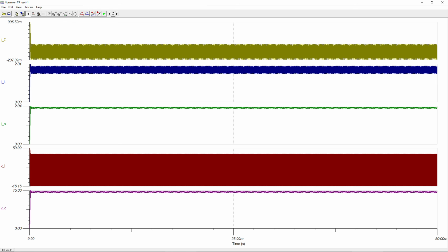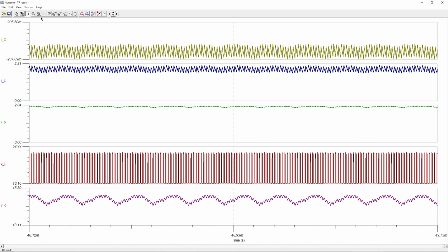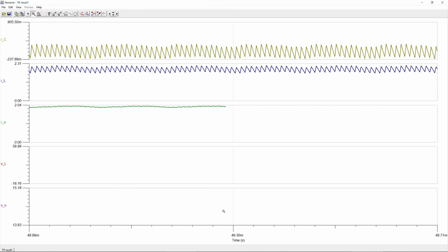You see here, as we have discussed, that indeed I go with I/O almost to 2 amps, so that is close to what we want. And here I see that I will also approach 15, but now I will again zoom in here and see the actual peak output voltage. Again, zoom in a little bit more so you can see how you can do that also yourself.